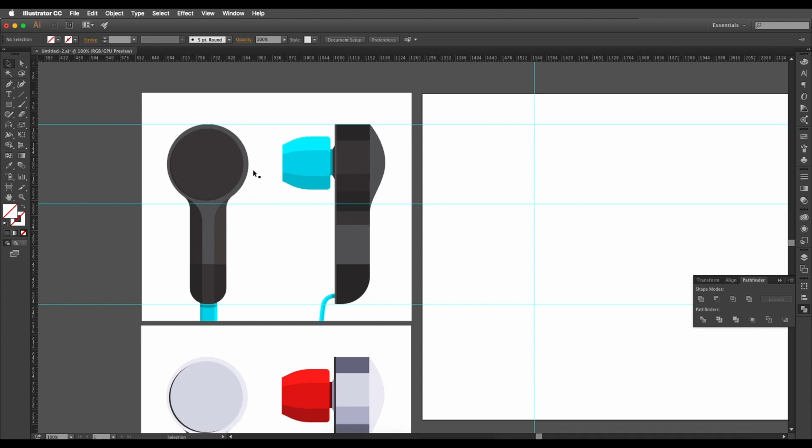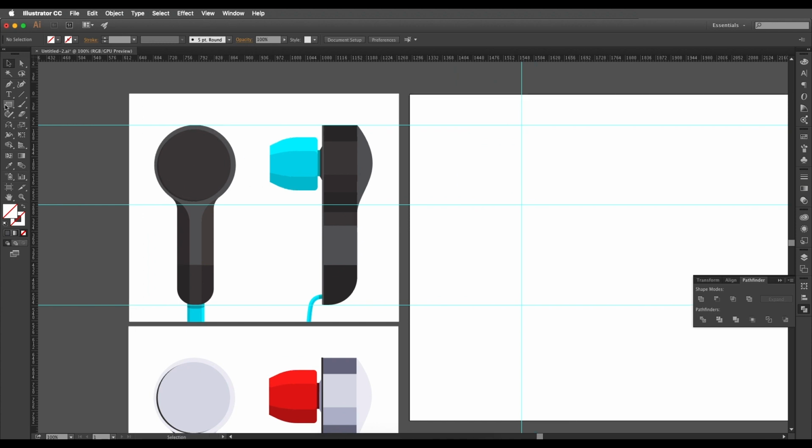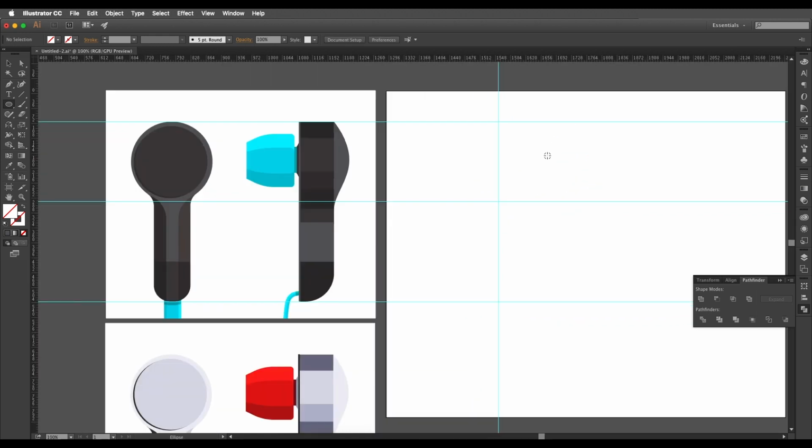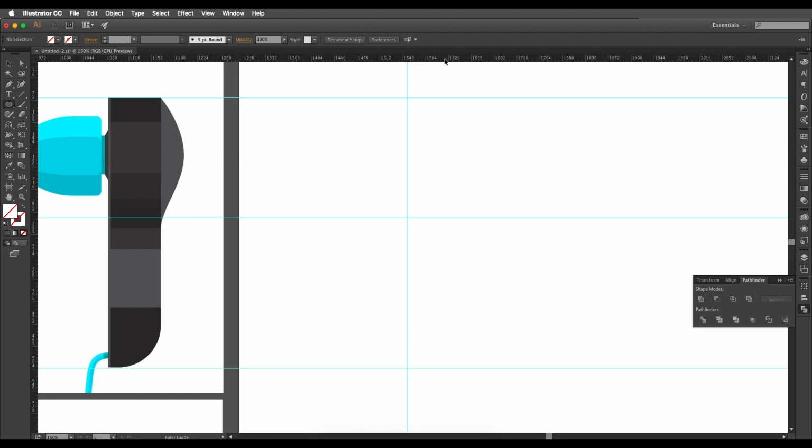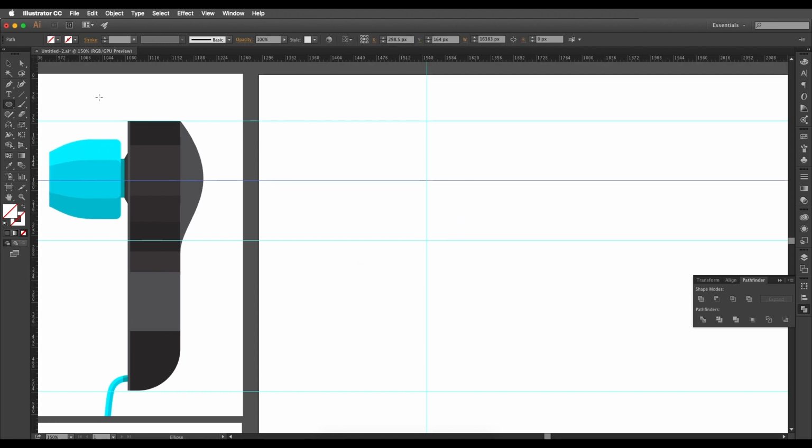Now the first step we're going to do is to create out the circle of this. So I'll select the ellipse tool and draw a circle like this. One more thing what I can do over here is let's bring out one more ruler and place it around here, and selecting these 3 rulers, I'll go to this alignment option where you can align your object or the rulers in basic proportion.